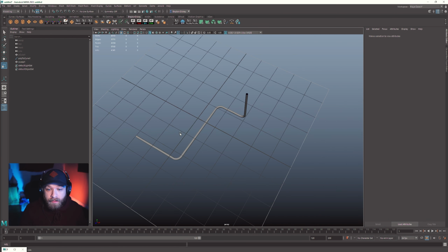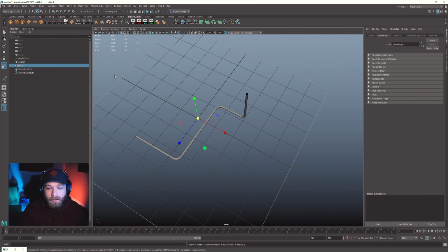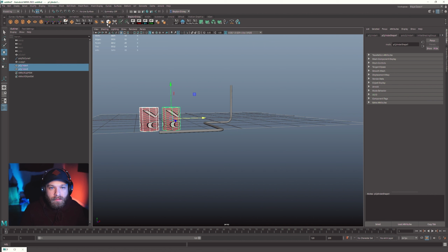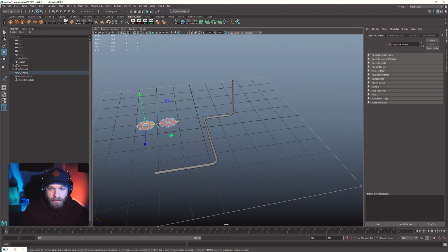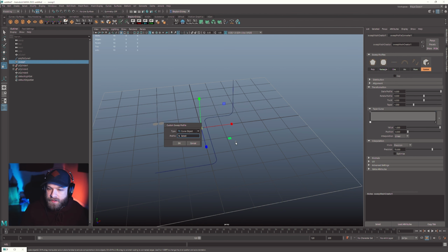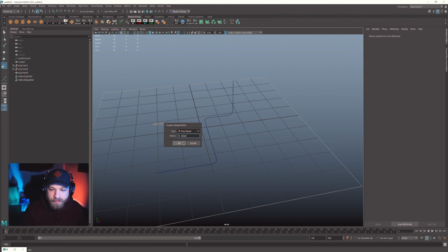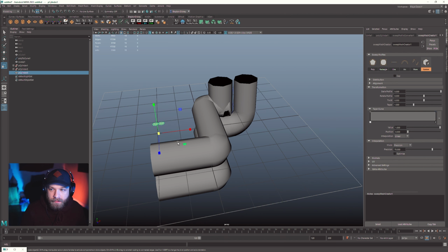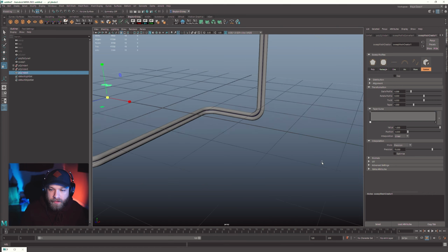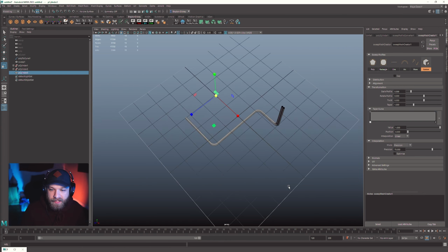And then even better, it still works with the ability to use the custom meshes here. So if we combine these, again, and get rid of these, move them a little closer together, make them a little smaller. We go back into our sweep mesh here, choose custom, do poly object, select these guys here, hit OK. Then you can see that it's now still doing the curve along that, and so it's making some really nice bends.